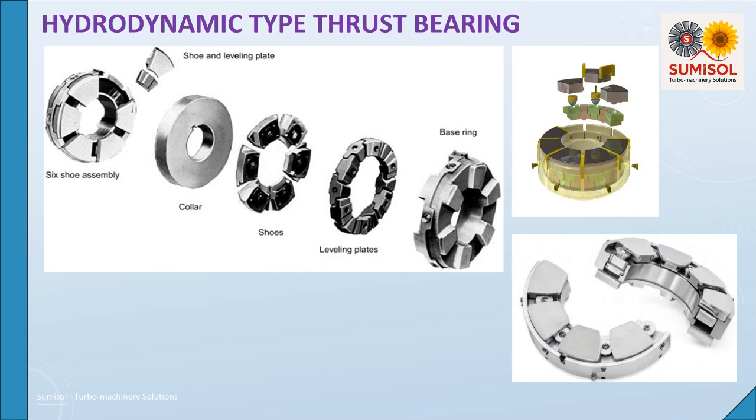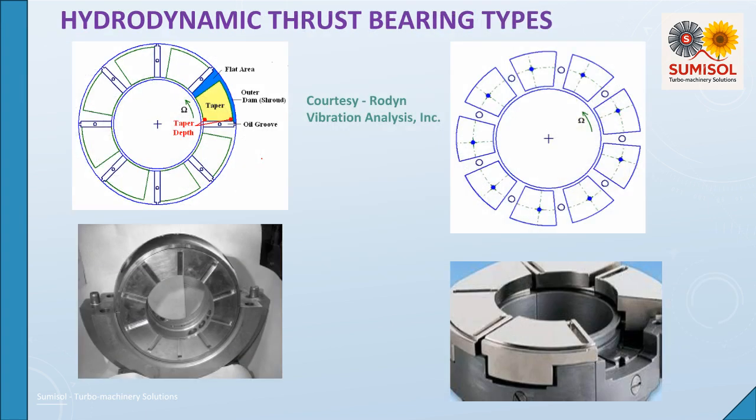In addition, pads can be supplied with center pivots for bidirectional running or offset pivots for increased load capacity and lower pad temperatures. There are normally two types of thrust bearings: non-equalizing and self-equalizing tilt pads, and then again tilting pad and taperland type. Tilting pad type has pivots shown in solid dots in the picture. Taperland bearings typically have about half the load capacity of tilt pad bearings.